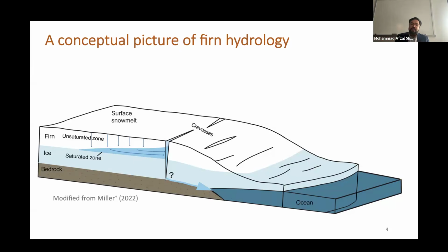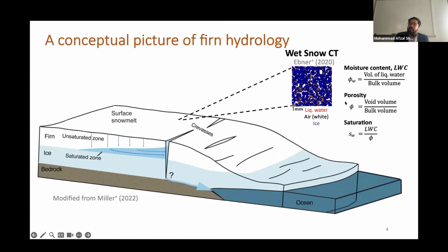This large-scale dynamics is governed by small-scale physics. If you put wet snow under a microscope, you would see a 3-phase system comprising liquid water, shown here in red color, air in white color, in between solid ice crystals, shown here in blue color. Models developed at such small scales, at millimeter scales, are not useful to solve problems at much larger kilometer scales.